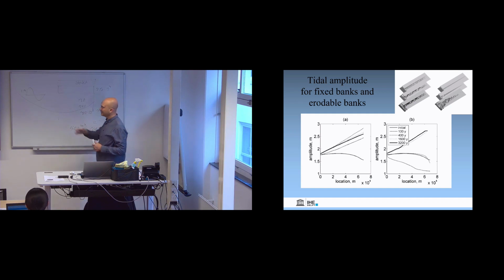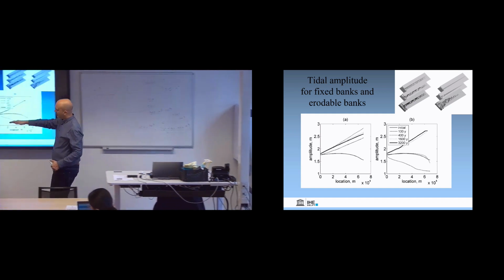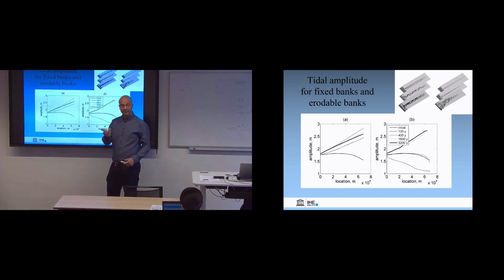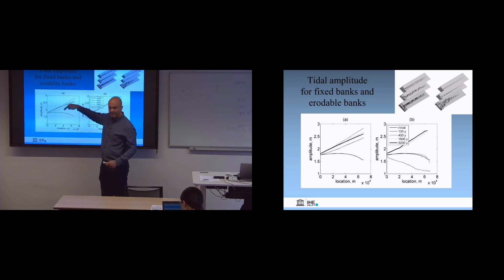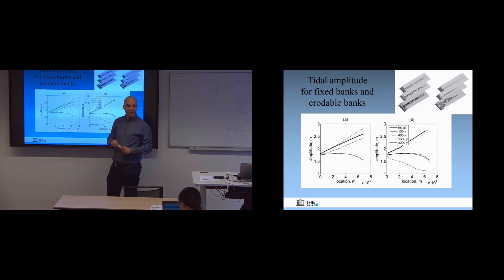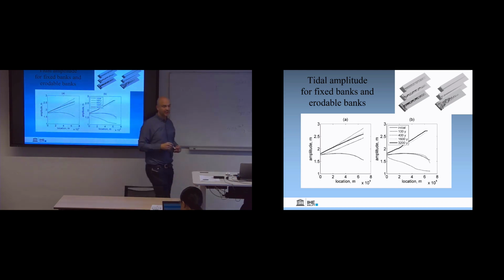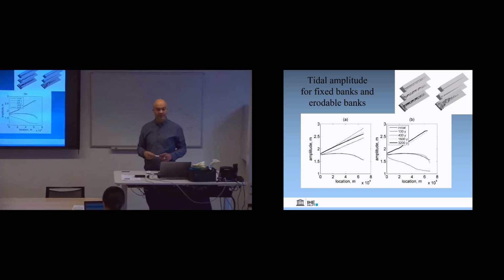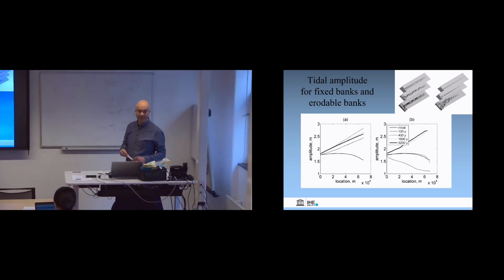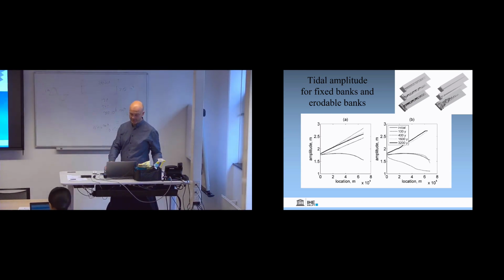That is happening because if it becomes deeper, you get rid of the friction. If you get rid of the friction, the resonant behavior becomes dominant. This is why the amplitude increases, and the resonant behavior results in the tidal amplification. So that's the entire story.